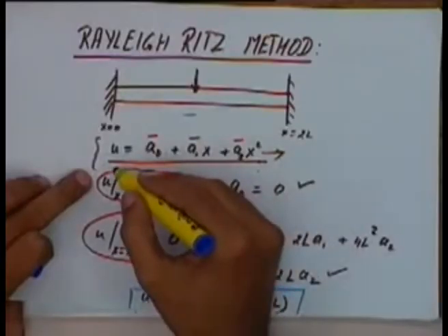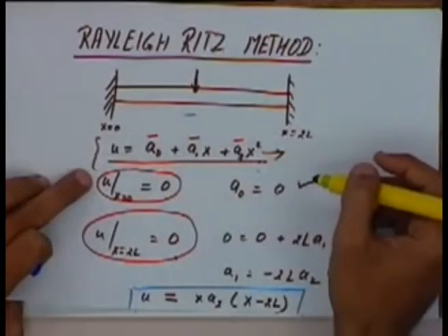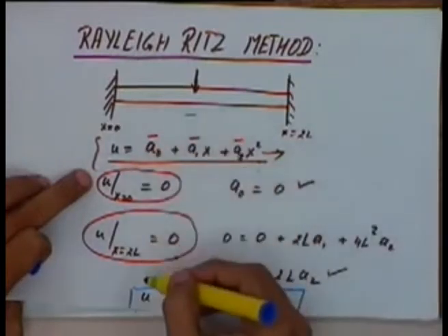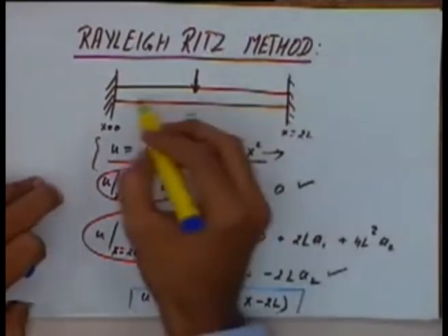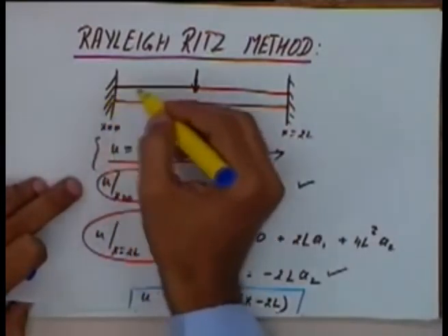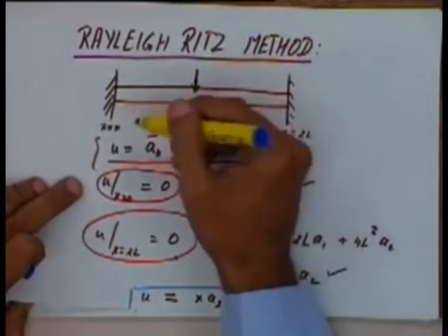Nevertheless, right now I have taken a simple expression for u. This can always be a more complicated thing. Just by applying the boundary conditions, you cannot solve the problem. But it's quite straightforward. Irrespective of what the load is, the boundary condition will be the same.